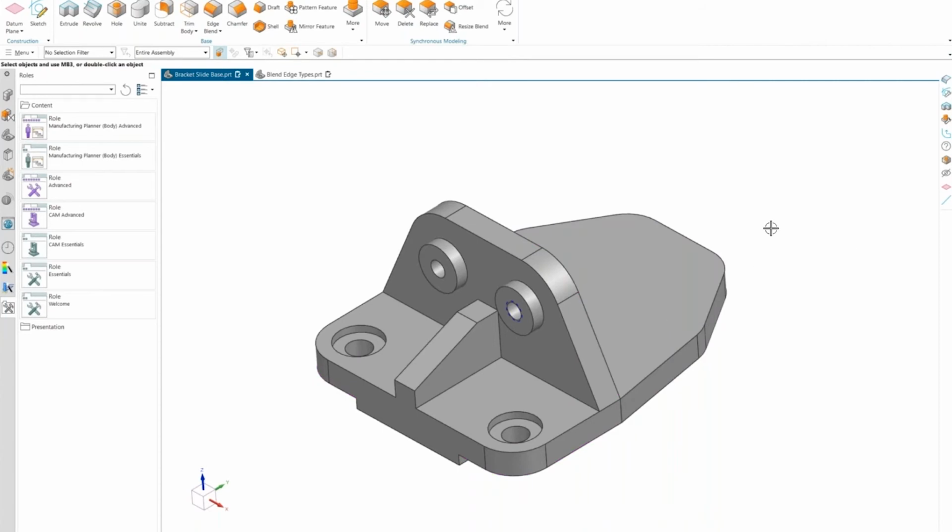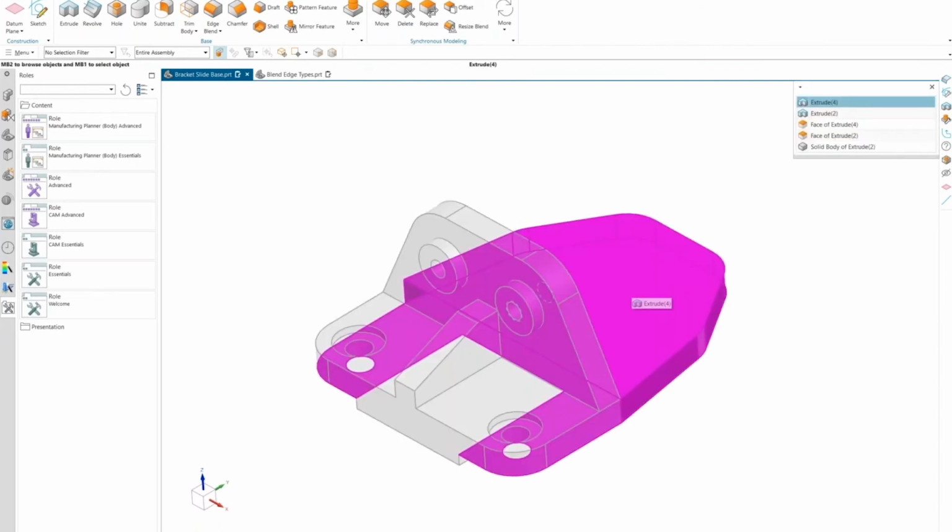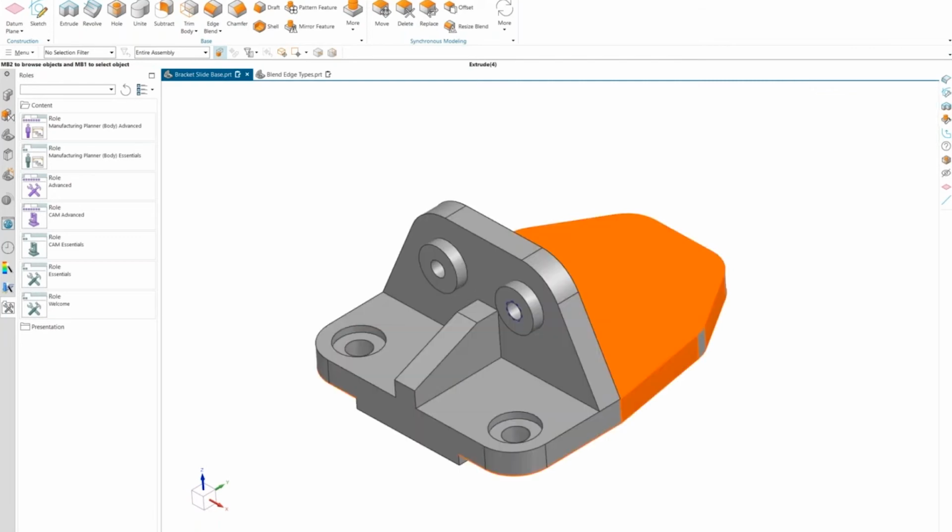However, I do still have access to the quick pick dialog box. All I have to do is hold down my mouse button 1 for a brief second and then let go, and I get that back on my screen. And I can then select specifically what I'm trying to grab. And so I like this a little bit better. So I always like pointing that one out in case it bothers other people.